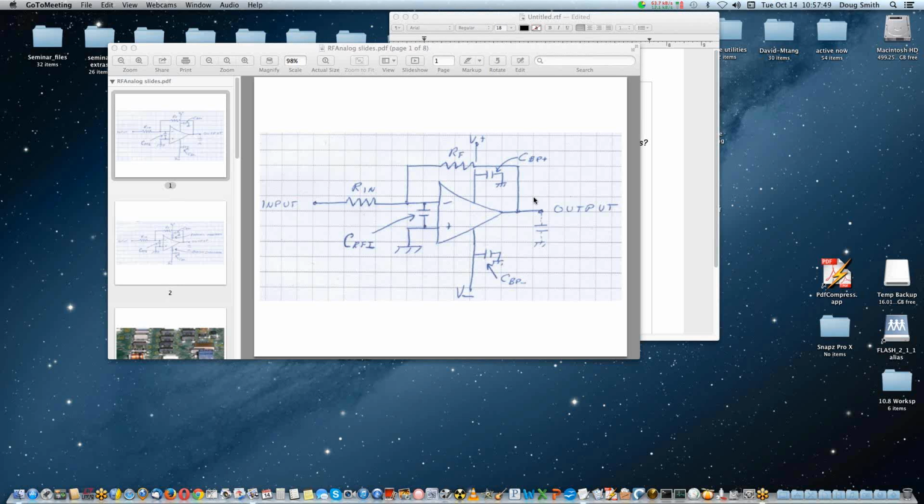If you're going to build a dipole into the coax, you need a balun at the end of the coax, a couple of ferrites or something, to prevent the shield of the coax being a third element.